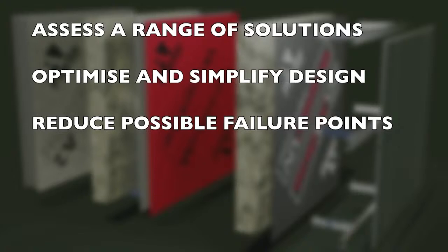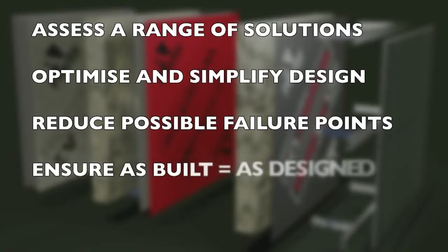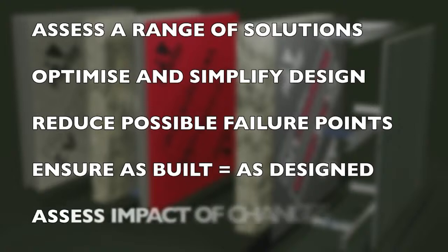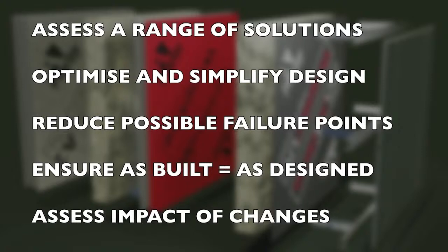When such highly optimised envelopes are designed, though, it's important to ensure they are built to the exact specification designed for, as superficially similar materials such as membranes and insulation panels may have different hygrothermal characteristics that render the assessment calculations invalid. If it does become necessary to change a specification, these changes should be reviewed fully and any calculations affected redone.